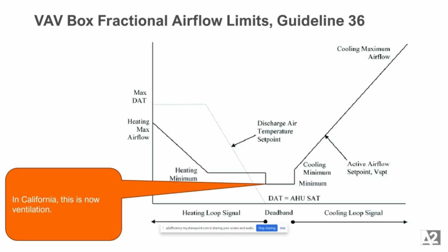So this is just a diagram taken from the guideline that shows where you might see the change in this airflow fraction depending on the set points for that building. And again, it's a relative chart. There are no numbers, but it is depicting this new sort of jog in the concept, right? We're now lowering the minimum during the dead band.